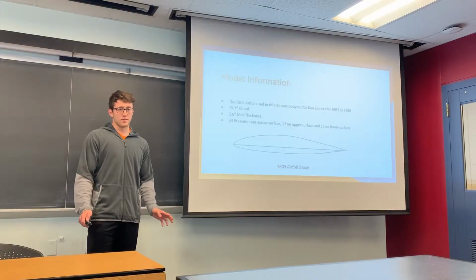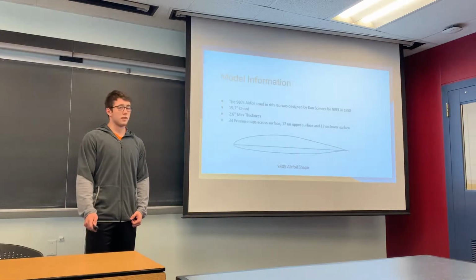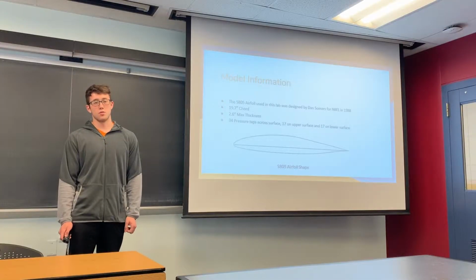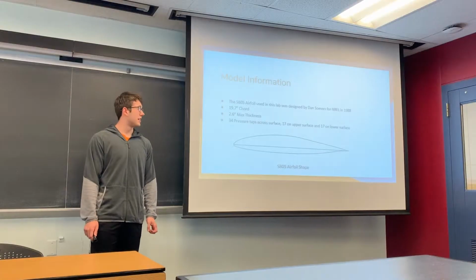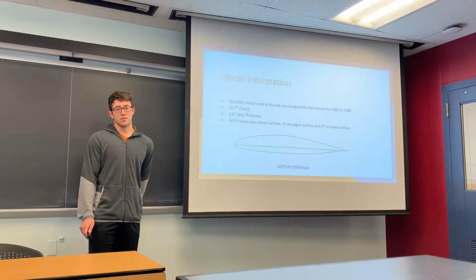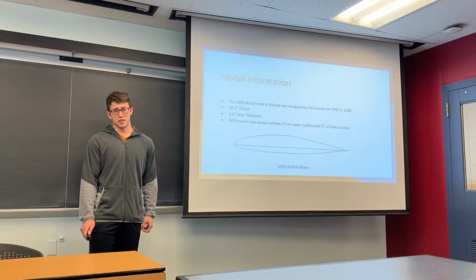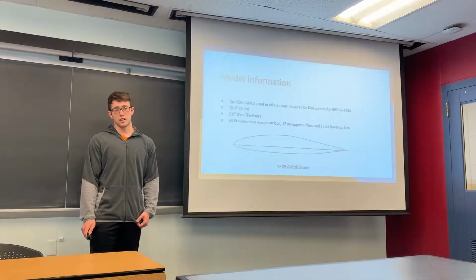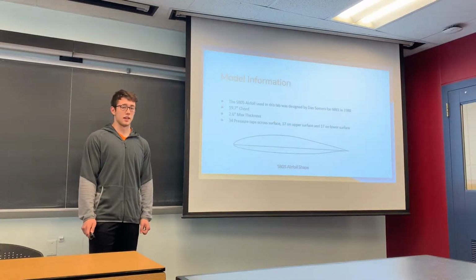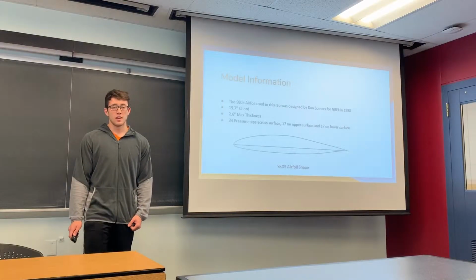And this comes into play for the lift coefficient versus drag coefficient graph. It should look similar to a bucket turned on its side, and this is called the laminar bucket. And it allows for very little drag over a wide range of lift coefficients, but drag increases very quickly outside of this bucket as the boundary layer transition moves quickly towards the leading edge of the airfoil.